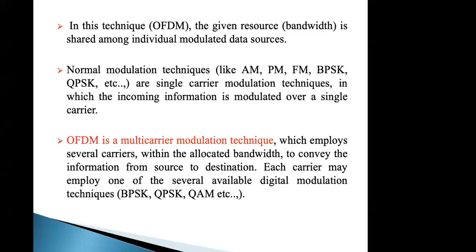So to avoid that, we want to communicate in a normal way, in a normal flat fading channel. So what is a flat fading channel? A flat fading channel, irrespective of the frequencies you are sending, gives the same uniformly distributed signal across your channel. That means your channel is flat during your entire band of operation. But when you move to high frequency bands, the channel is not flat. It becomes a frequency selective channel.